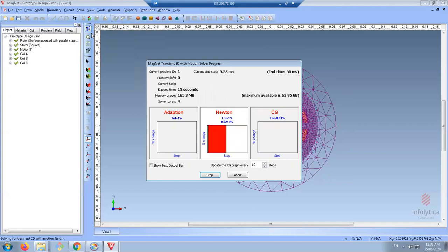But to be honest, MotorSolve makes life way easier because you don't really need to set the mesh density, the solver properties, motion analysis. In terms of motion analysis, yeah, you do something, but in general, it's just automated. It automates the process. But here, in Magnet, you have more flexibility, but you need to know what you are doing. You should make sure that you set the settings and adjustments correctly.